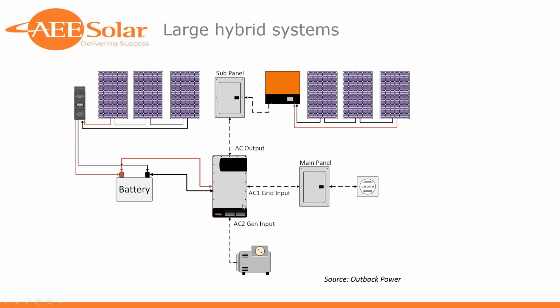What's not indicated on this diagram is, in my opinion, you typically want to have a relay between the subpanel and the PV inverter, so that if this PV inverter can't take curtailment decisions, you've got a way of turning it off and still supplying this subpanel with power.